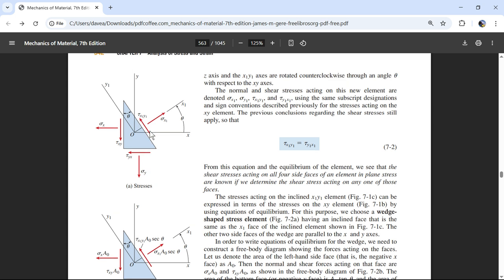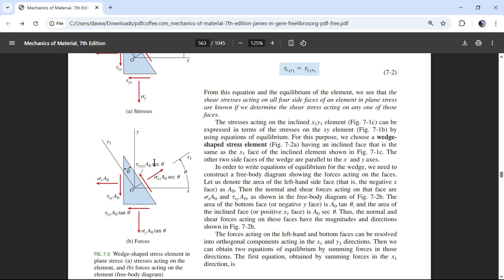So that was just showing why we talked about that: secant is 1 over cosine, and if I took the area and divided it by a smaller number, that's going to give me the bigger number. So even just that should be the alarm bells that A divided by cosine must be a hypotenuse, from a side that's given the cosine component. So that's what you can see there. And so then this is force. This is going to be the pressure in PSI, or newtons per meter squared, and then the area of this face.